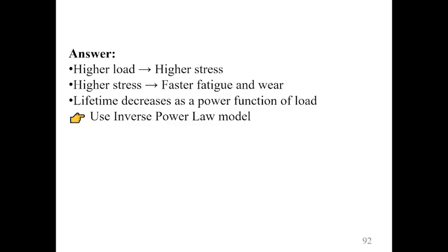The inverse power law model captures this relationship mathematically, where lifetime is inversely proportional to stress raised to a certain power. This model is widely used in fatigue analysis and mechanical reliability studies. It allows you to predict system behavior under normal operating loads based on accelerated testing at higher stress levels.